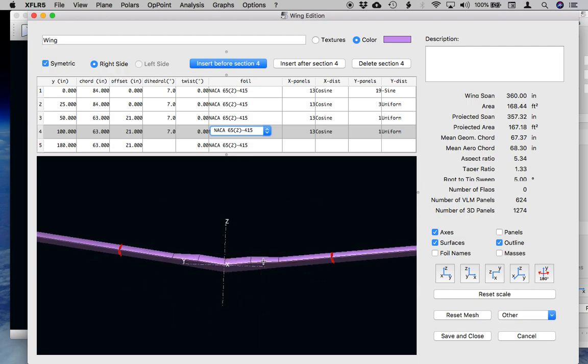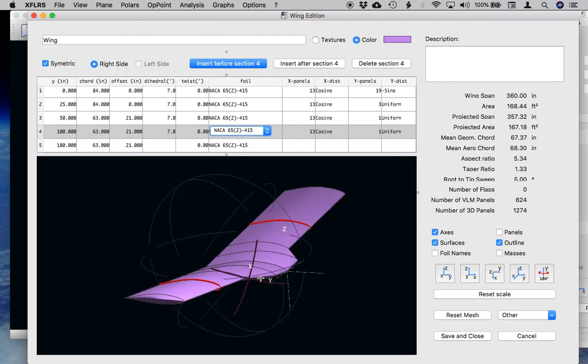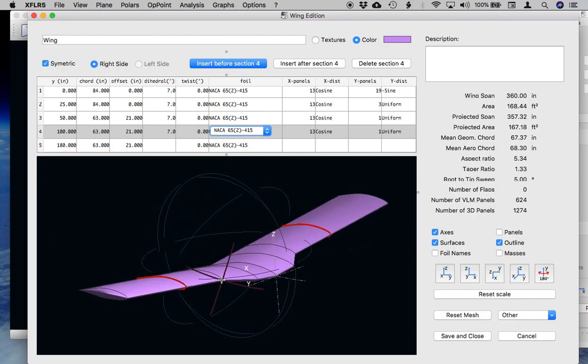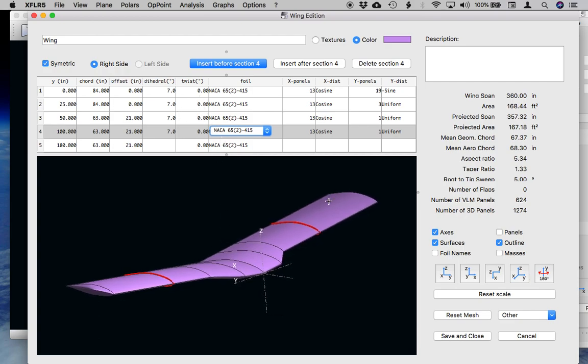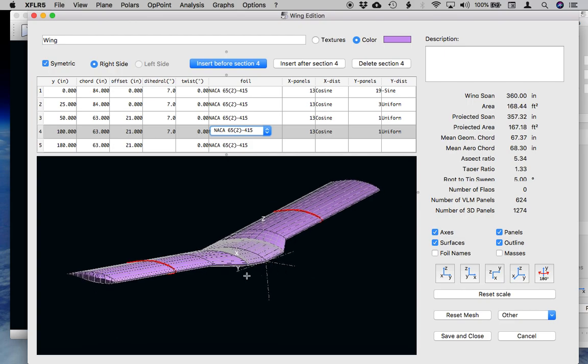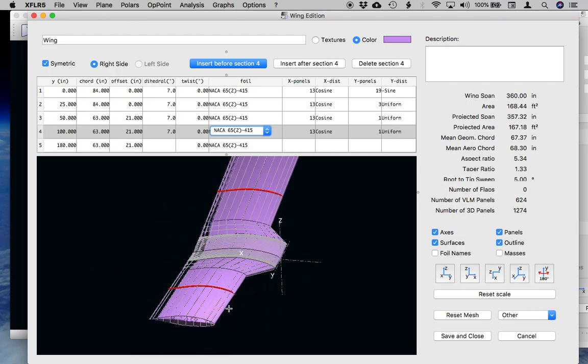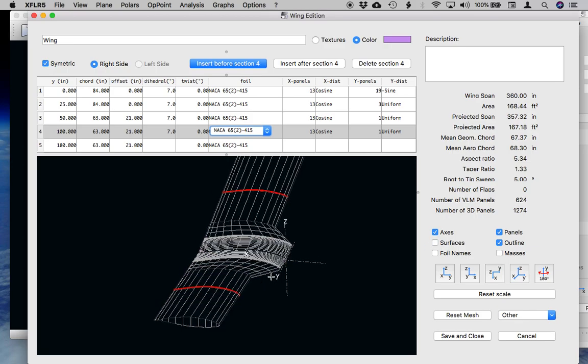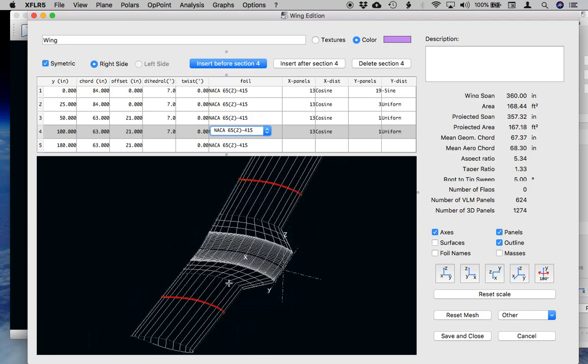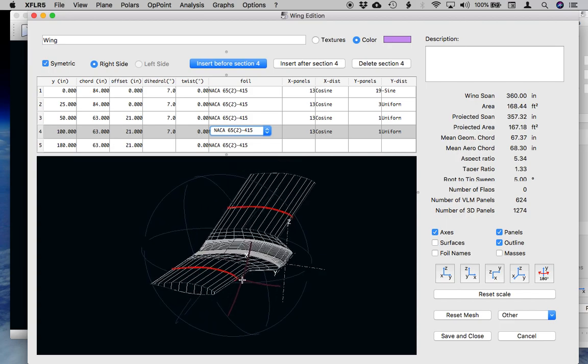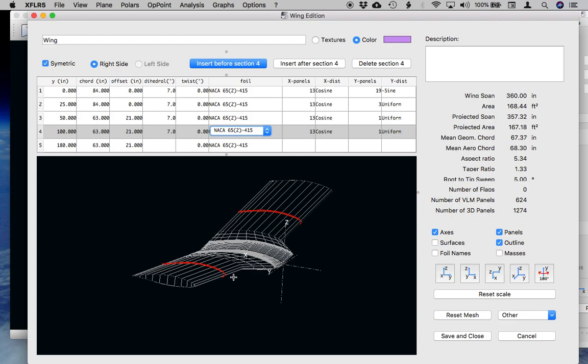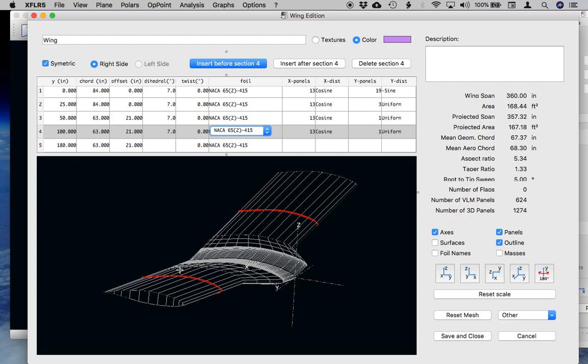So this is fairly rudimentary, right? You can add a lot of details in here about what this actual wing planform is going to look like, adding things such as twist, changing the number of panels that you have. Don't worry about editing any of that, but if you want to come back later and, for example, increase the resolution of the vortex lattice panels that you have, you can change that as well. So these are the computational elements that will be running for that three-dimensional vortex lattice case. But this will be good enough to get us started, and then we can come back and adapt this and change this as needed.